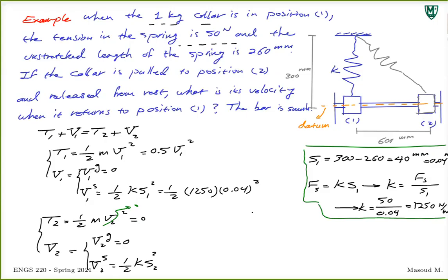It's spring stiffness. As long as we don't stretch the spring too much that it deforms, or compress it too much that it's out of its range, K is the same. And we're dealing with linear springs here, so we are fine. Just one K always for the spring. We have to calculate S, or S2 better to say.